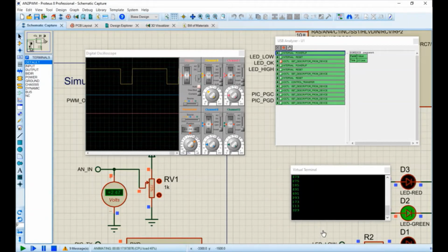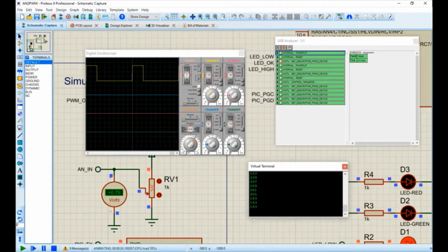This is actually a great debugging tool, and I used this while developing the microcontroller code to debug and to get everything working nicely for the webinar. And at this stage everything is polished and working well. You can see the voltage changing as we move the potentiometer around, and we can also see the value coming out on the UART is changing.